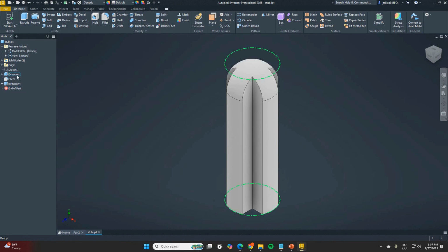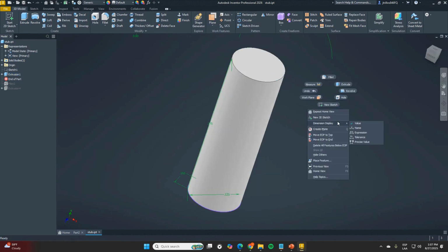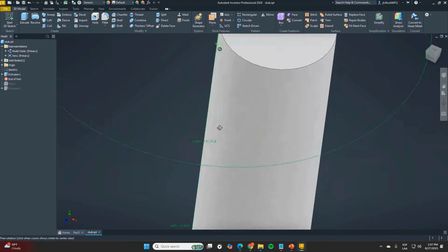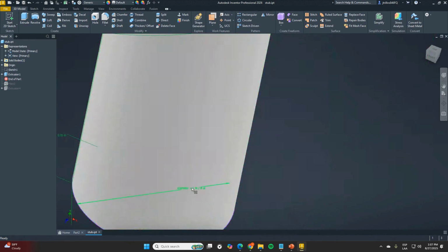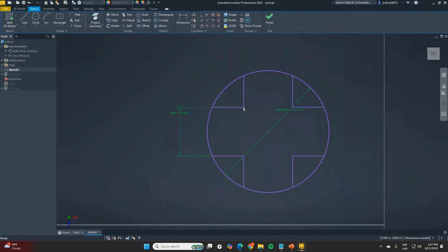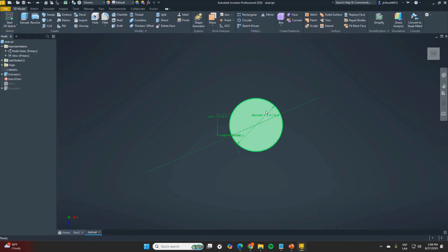In this case, what I got from a feature is an extrusion, right? That's basically constructed with a certain height and a certain diameter, okay? So I got the height right here, I got the diameter parameter down there, and I have a width parameter that's basically from the sketch I'm getting right here, okay? So my sketch right now is kind of free in some sort of way, in the sense that it can be moved. It doesn't have any external references. That's going to be very important, right?